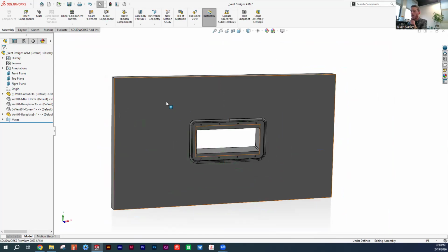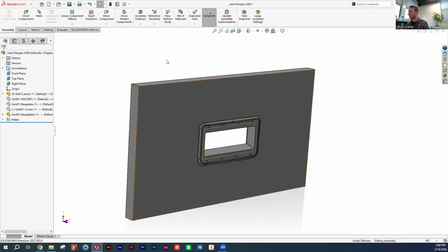If your part is fully dimensioned, then you won't see the negative sign here. Fully dimensioning means it's fully fixed. If it is not fully dimensioned, which is okay, it'll show that dash mark right there. That means that it has freedom to move. And for our door, that's actually what we want, so that we can swing it up and down. So I have that part positioned.